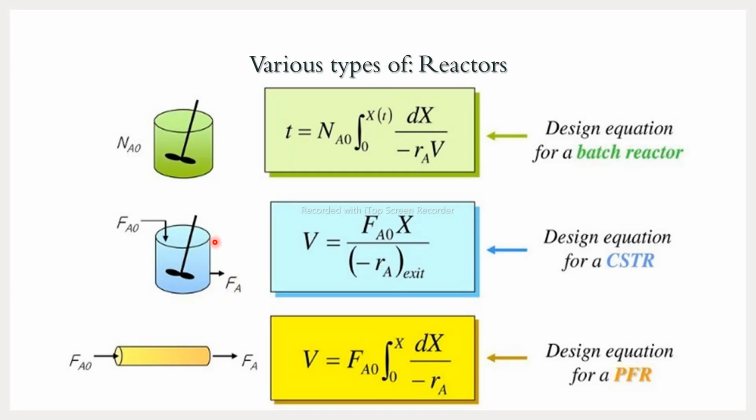So their reaction rate is higher at a particular temperature. Let's say they give the highest yield at 50 degrees centigrade, and you are continuously maintaining the hot water temperature outside the reactor at 50 degrees centigrade with the help of hot water flow. There may be jackets, limpets, or coils, and there is a temperature controller present at the outlet. If it senses that the temperature is going down, it will increase the hot water flow in the jacket to maintain the optimum temperature.